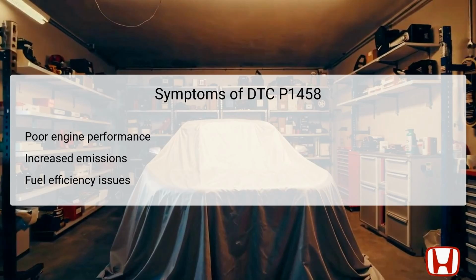The symptoms associated with DTC P1458 can be quite noticeable. One of the most common signs is poor engine performance, which may manifest as hesitation during acceleration or a decrease in overall power. Increased emissions are another critical symptom, as the ECM may not manage the air-fuel mixture effectively due to faulty sensor readings, potentially leading to failed emissions tests.